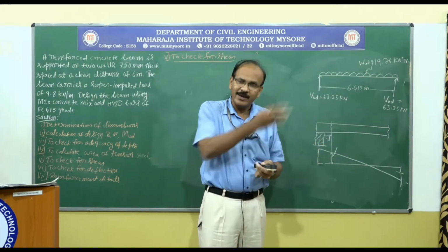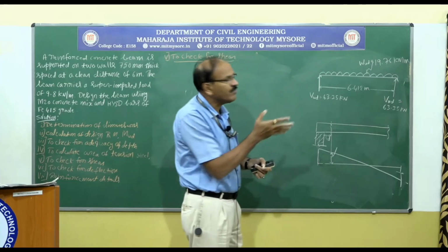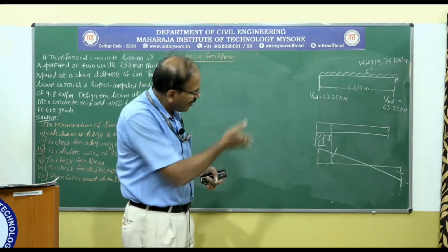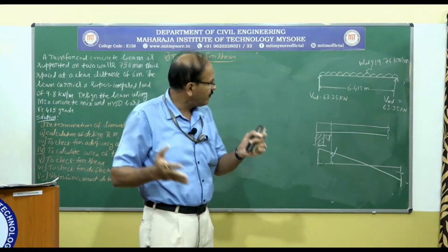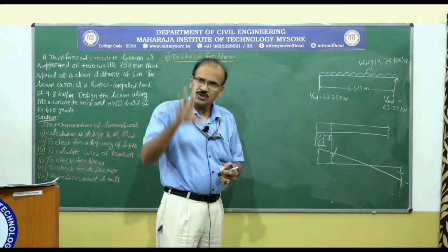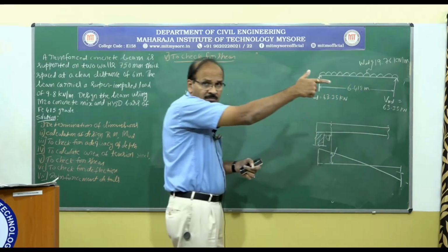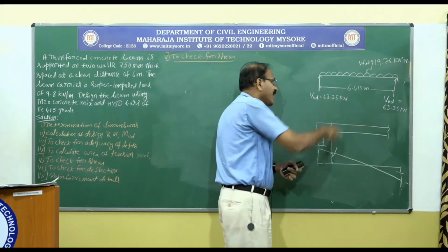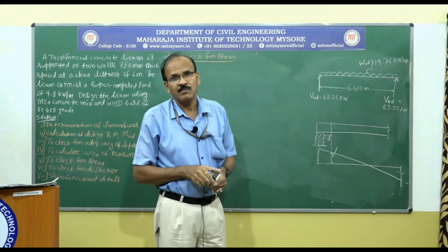Okay, that error I am committing is on the safer side. I am doing that just to save time and also to avoid complexity of the problem. I can go ahead and do everything, but within the given time frame in the examination, if you keep doing all those things, the time will not be enough for you. Just to avoid that, I have taken the effective span and whatever the design load, and I have taken the reaction. Okay, so that reaction is going to be taken as the design shear force. Is it clear to you?